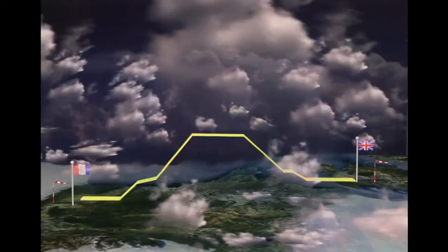Normal law is modified depending on the phase of flight. It operates in 3 modes. Ground mode operates on the ground when the aircraft is electrically and hydraulically powered. Controls are conventional. Flight mode operates in the air after a gradual transition from ground mode, just after liftoff. Flare mode modifies flight mode to introduce a conventional feel to the landing phase. Will be discussed later in this module.